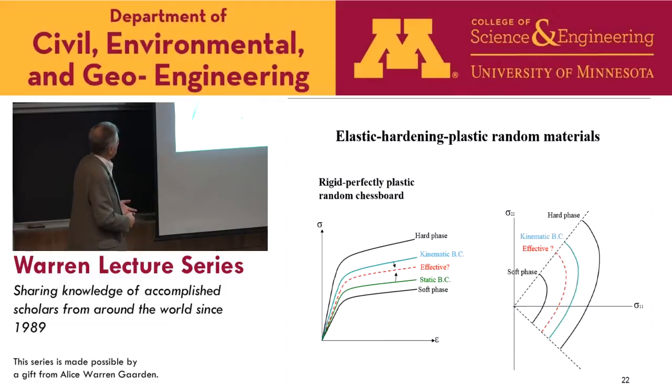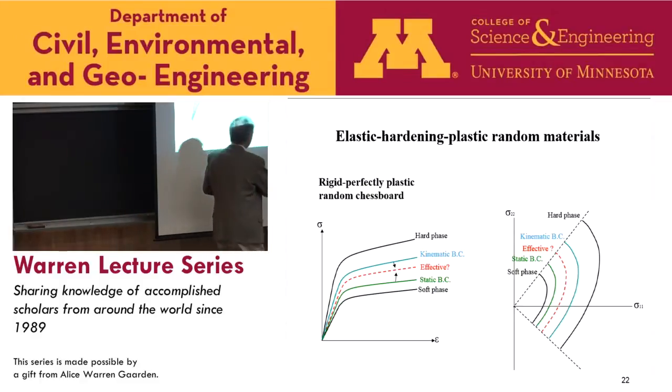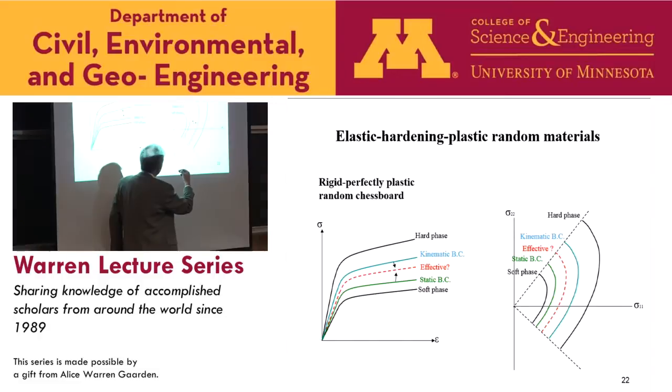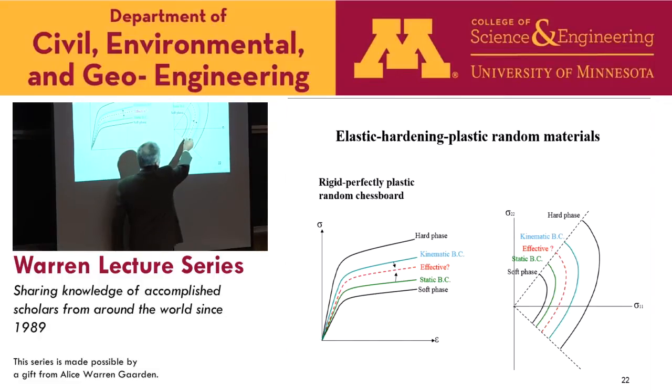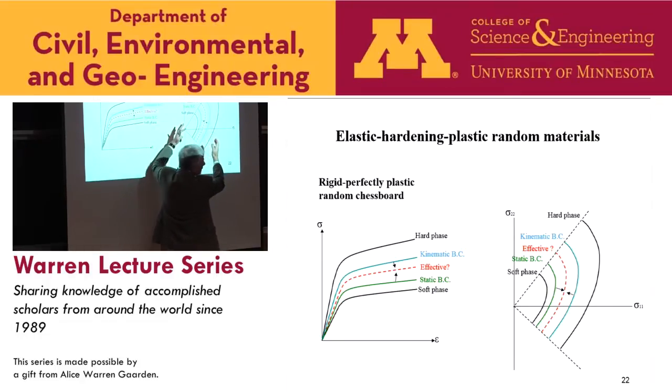And one can get this approach towards the effective yield surface of the idealized homogenized elasto-plastic material in terms of those bounds. So there's a hierarchy of inclusions which I can write. Now, not inclusions in terms of the stiffness tensor and compliance that I showed earlier, but in terms of yield surfaces which contain ever smaller regions.